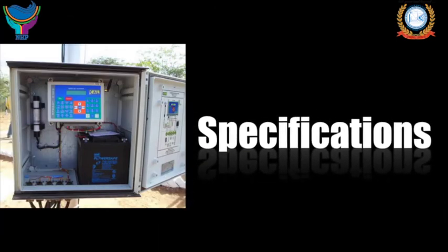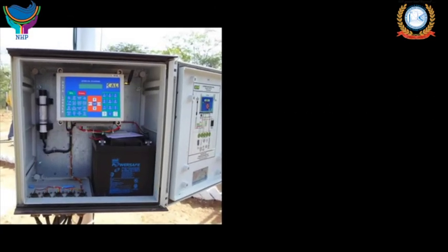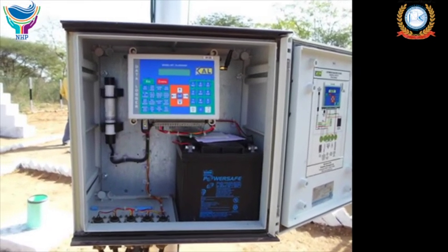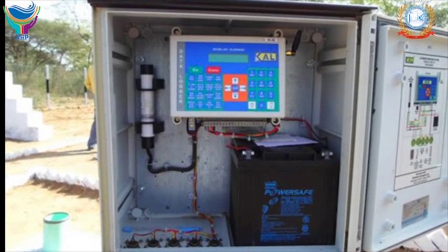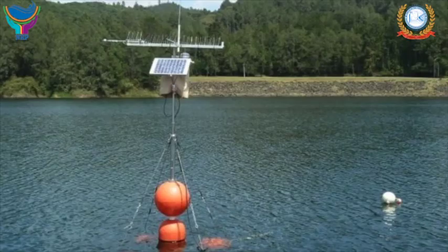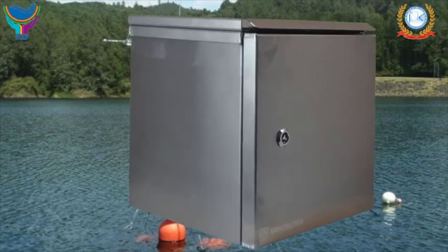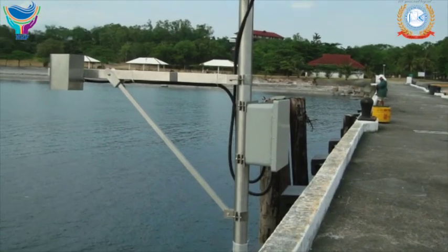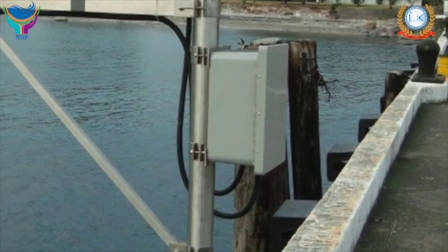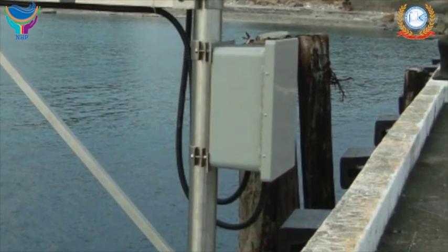Enclosure and wiring specifications. Instruments should be secured inside the instrument shelter in an orderly fashion. All wiring and cables should be well organized, clearly labeled and secured. The enclosure must be sealed and secured in a NEMA type 4 enclosure so as to prevent water and insects from entering the enclosure. Wires leading in and out of the enclosure must be properly secured and protected from sharp edges.